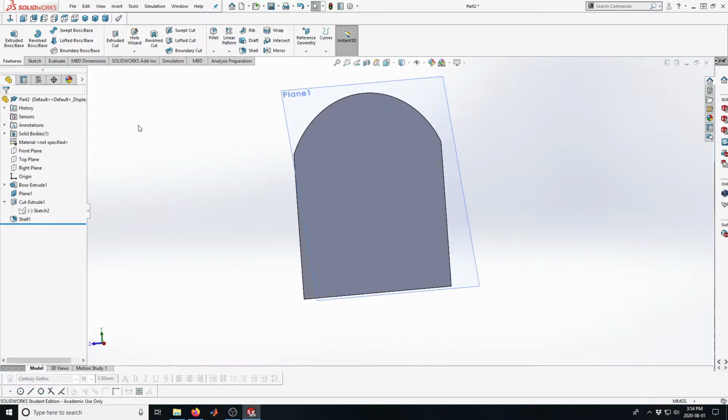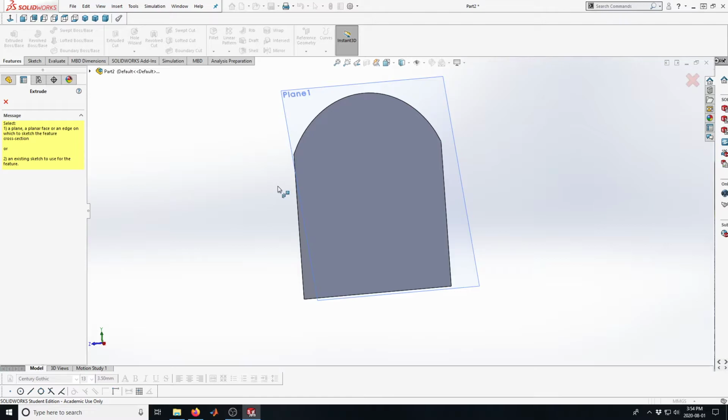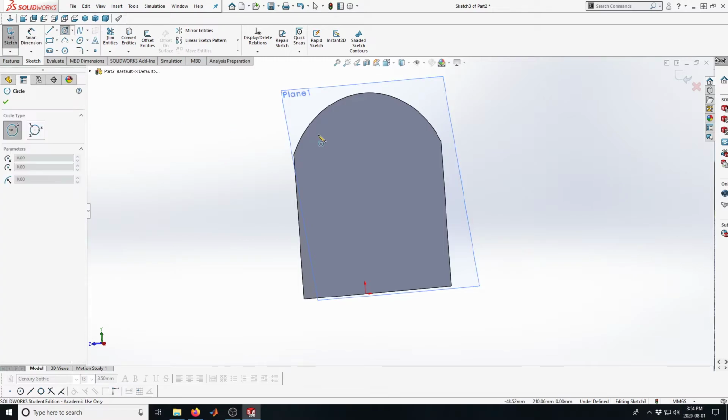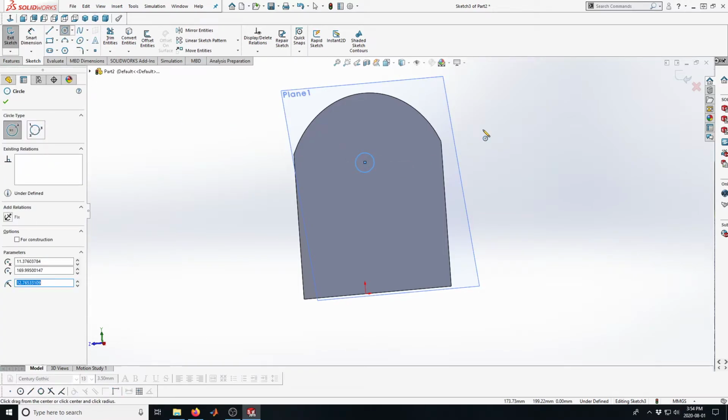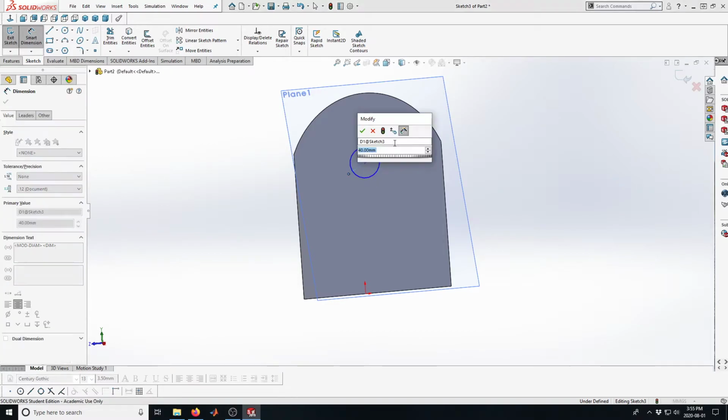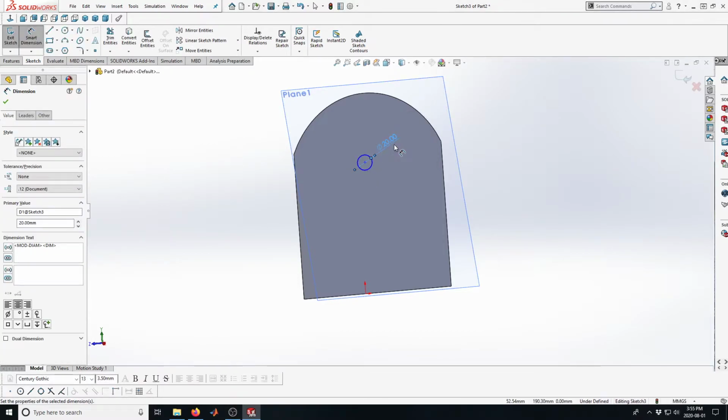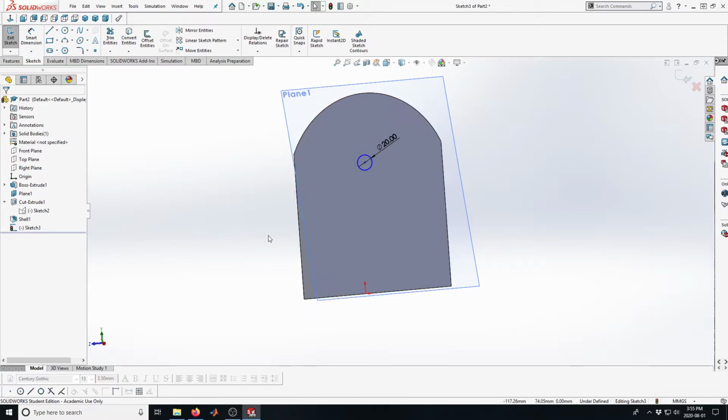In order for the birds to get in and out, we want to make maybe an entrance hole for it. So I'm going to select this face to cut on, and I'm going to make a hole. And that hole is going to be 20 millimeters. Oops, I guess I should probably use the dimension tool for that. Yeah, that's all right. We'll make that 20. That seems like a really big birdhouse, but hey, it's my backyard. I can do whatever I like.